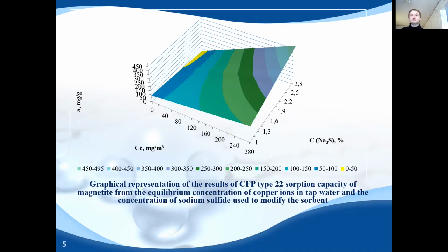Increasing the sorption capacity of magnetite for copper by increasing the ratio K, in addition to the positive value, has significant disadvantages. First of all, magnetite obtained at K 1 to 2 has the highest magnetic characteristics, which simplifies its separation from water, has the highest sludge density and the highest chemical resistance because it has a crystalline structure.